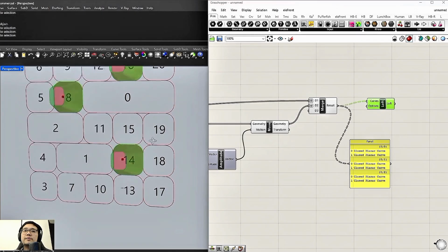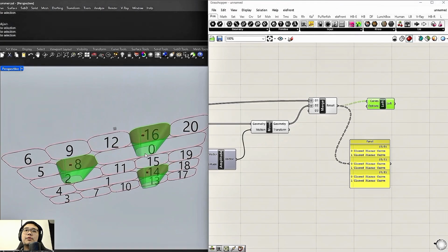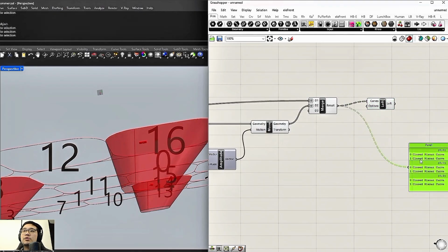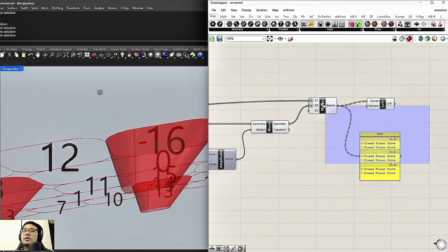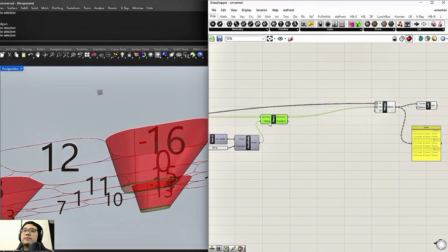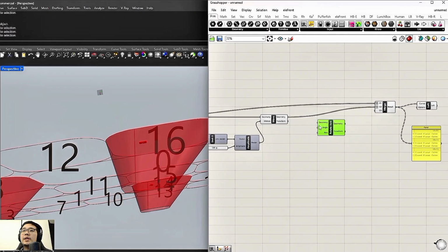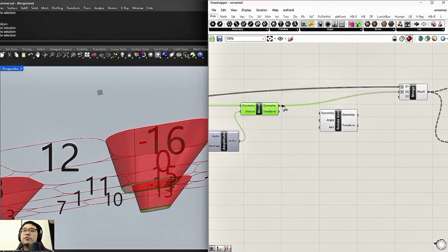So this is great, but I want to add in the orientation of the window, the look towards the left. So I want to create some angle here. So I'm going to grab all this stuff, move to the right. I need to add in a rotation component. Rotate object around the axis, which is fine. Let's grab that. So I want to rotate this geometry.